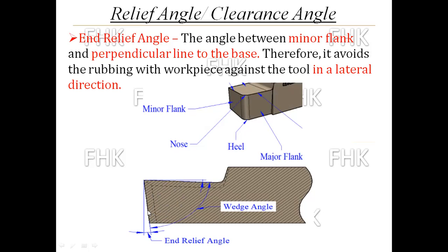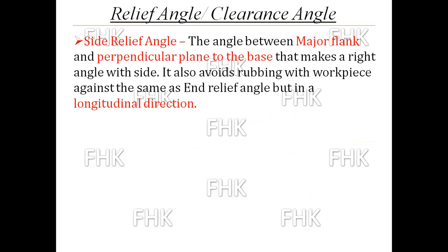So to increase the life, a small angle is provided here. That angle is called the end relief angle, and that is in the lateral direction. Clear?